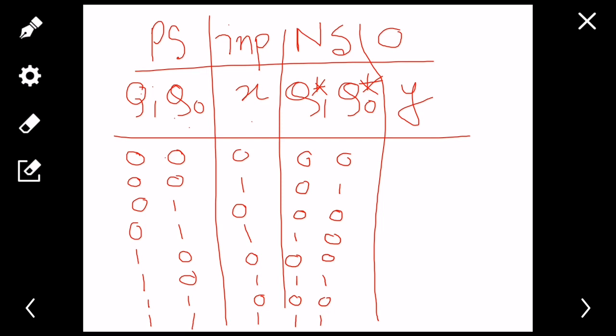If you recall properly, you need to detect three or more consecutive ones, and the last state fulfills the condition of more consecutive ones coming through the input line. So the output will be 0 at every position till I reach this state, where it will be 1.